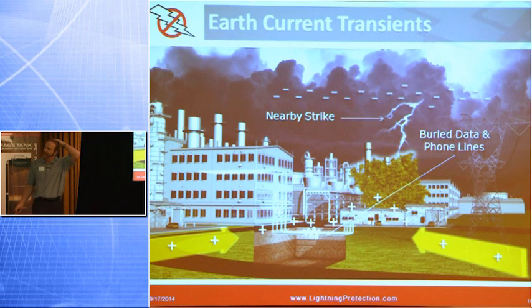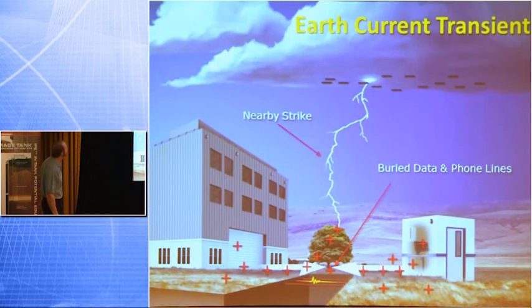And we'll talk about this a little bit later on, but when you have a shutdown, you have major problems. You can't turn the process right back online. A lot of these processes take about 8 hours to shut down and bring back up. If it's in a refinery scenario, you're flaring the product, so you're burning money, and you're not producing. These can easily cost in excess of $250,000 to $1 million per shutdown caused by a false signal. So this is another secondary effect that is a big problem in the refining industry.